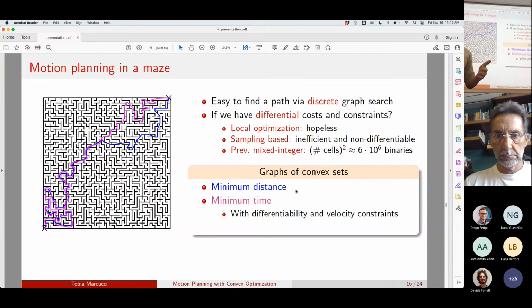So the robot will always go straight when you solve the convex relaxation. The first information you get out of your optimization problem is the solution of the convex relaxation. Then you can do branch and bound. But the initial information is to go straight to the goal independently of the environment. While our convex relaxation, having this underlying graph structure, is much more informative, and most of the time is actually exact.